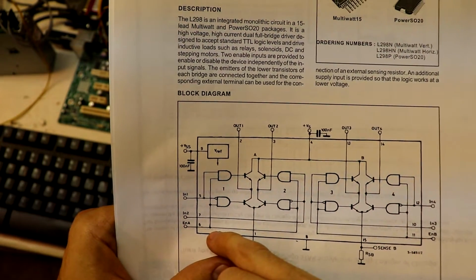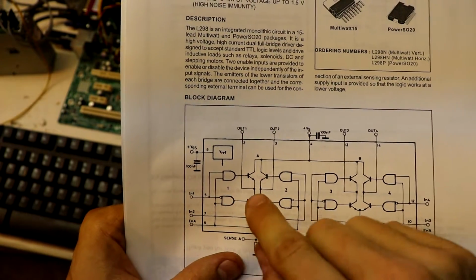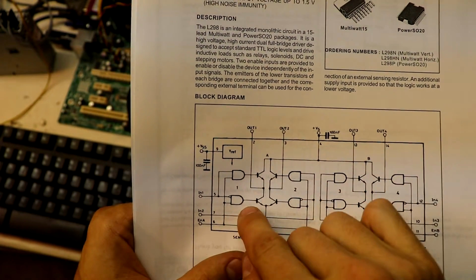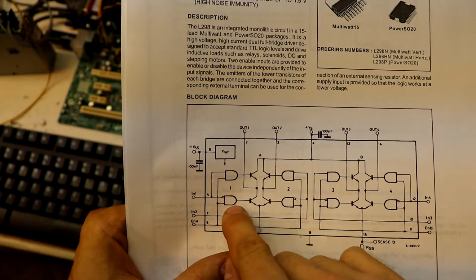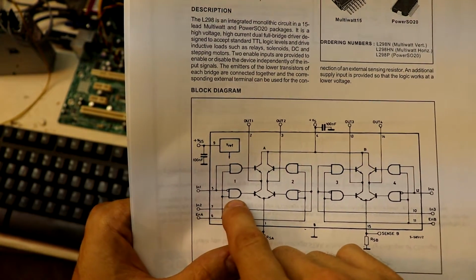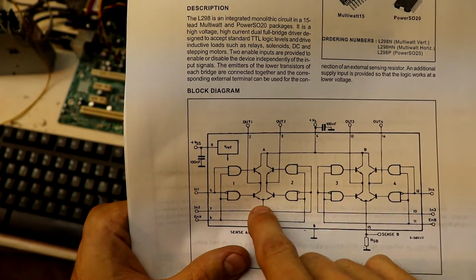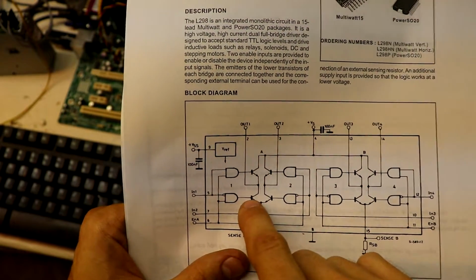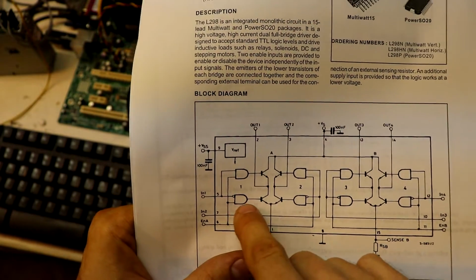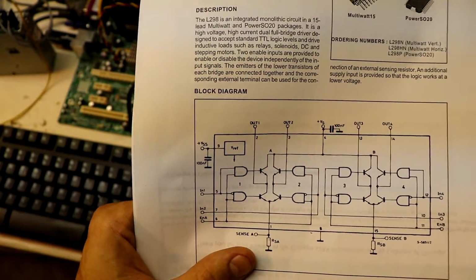So this enable connection goes to this piece of logic circuitry. It is not important to know if this is an AND, XOR, or different types of logic. Really, what you have to notice here is that this enable connection is simply connected over to the base of this transistor. Meaning that this enable pin, all it does in conjunction with the inputs is turn on the base of this transistor to make the power flow through the outputs, right?